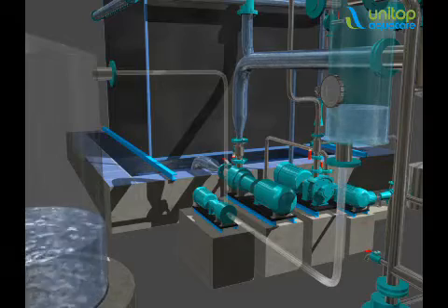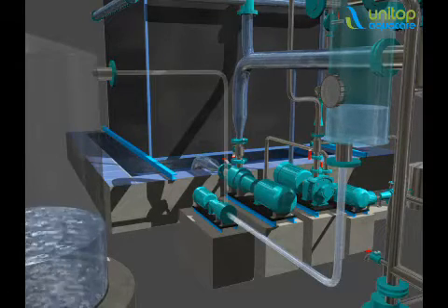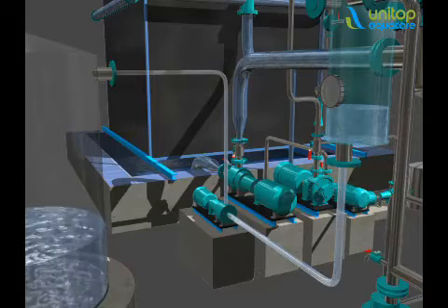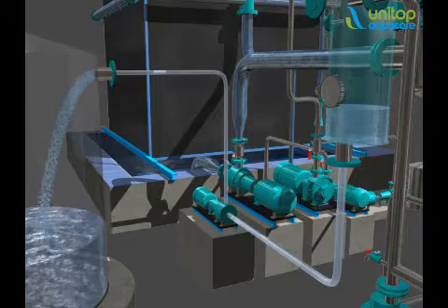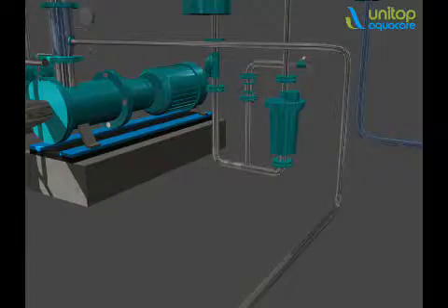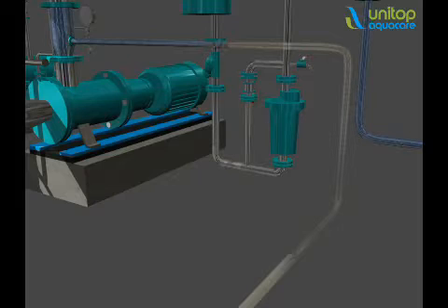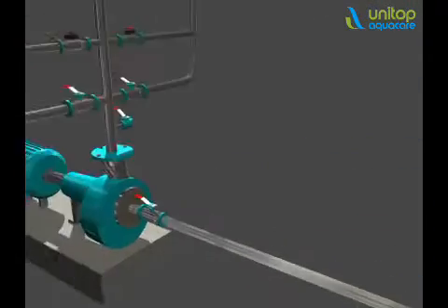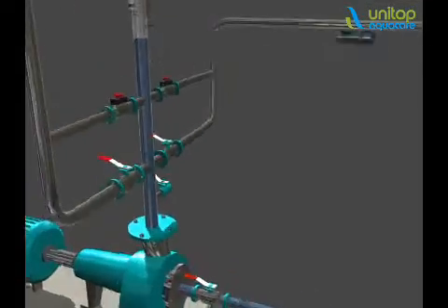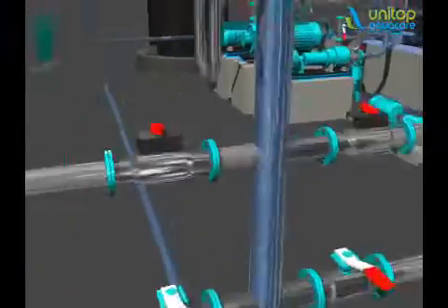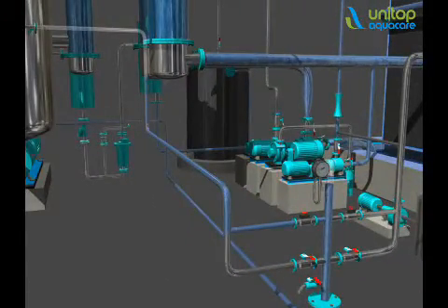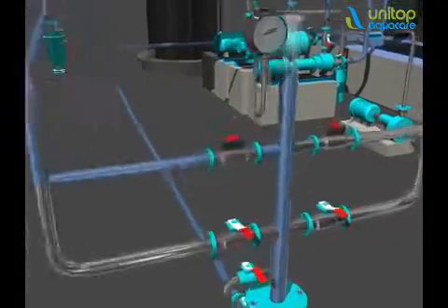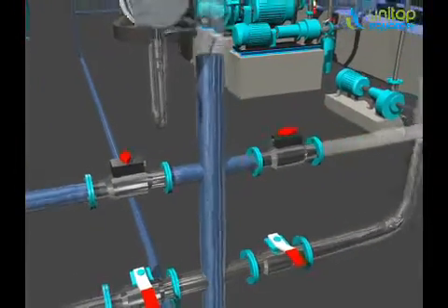Generating the vapor condensate with TDS. The condensate, usually with a TDS of not above 200 ppm, can be used in a unit based on the requirement. From the last stage, the product pump pumps the concentrate for further drying operations. Based on the nature of salt and the crystallizing properties, the various options used for drying are solar pond, wiped or agitated thin film dryer, crystallizer with pusher centrifuge, and spray dryer.